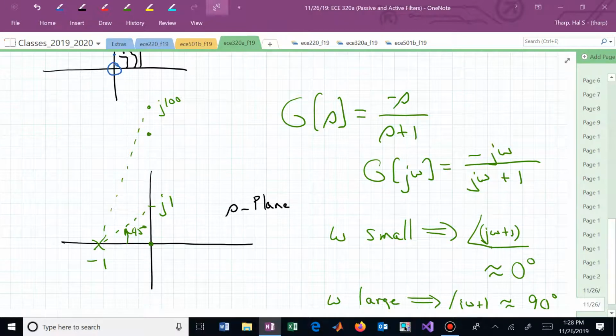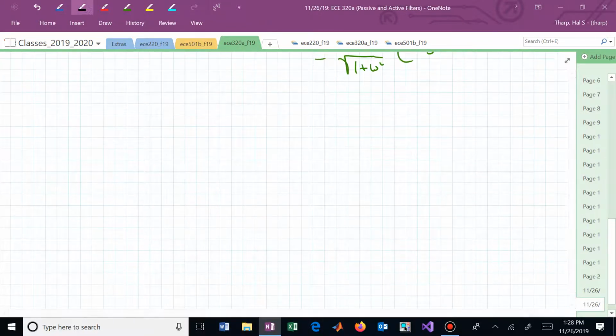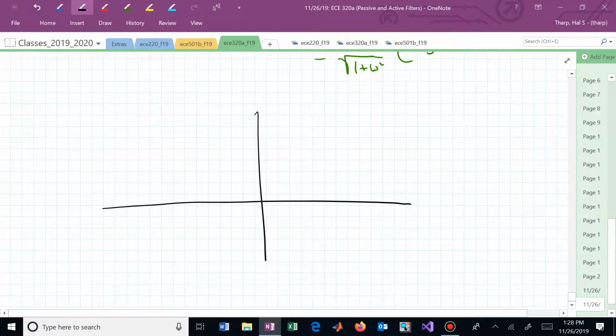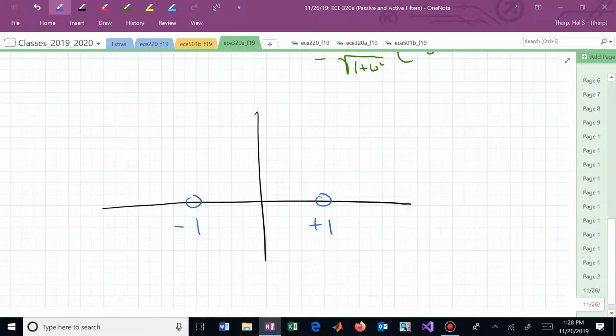in terms of minimum phase, we could say something like the following. Suppose that I now had a 0 here at, well, let's just be very concrete, at minus 1 versus a 0 at plus 1. And we're comparing the characteristics of these two zeros. If I'm now looking at the magnitude relative to the one in the left half plane, I'm looking at that hypotenuse.